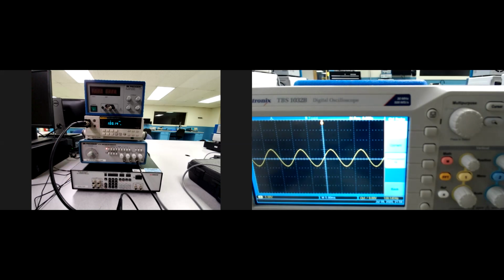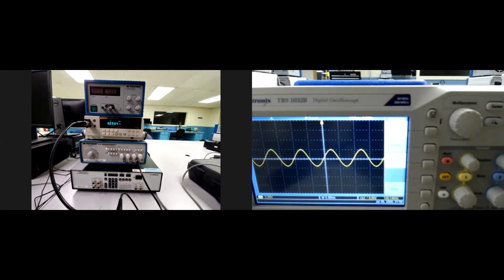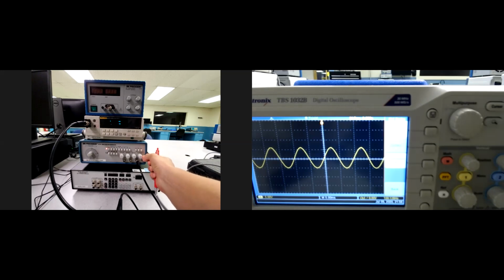Now let's check the voltage on this signal. So I'm gonna do voltage AC. And if you take a look at the multimeter, we have 3.8 volts RMS, but step 2 is saying that we want to have it at a maximum amplitude. So I'm gonna crank up the output level knob all the way.